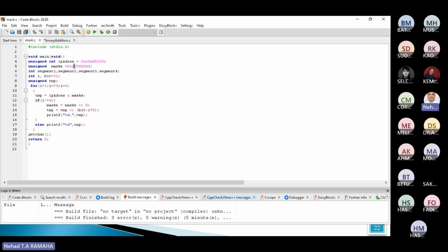Then this mask will be shifted every time by 8 digits, meaning 8 digits in the bits, or in the binary, means 2 digits in the hexadecimal. So this means this FF will be shifted here, next time here, next time here as mask, because we know this mask tells us which 2 digits in the hexadecimal or 8 digits in the binary will be taken.